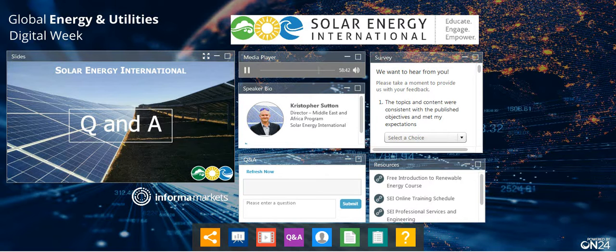What was the next one then, Michelle, or the other part of that? Yes. Can you use your solar system at night? Only with a battery. The PV modules, the solar panels, only produce output that is instantaneous to the sunshine. So if it's a grid-connected system with no batteries, we get solar during the day, and then we use the utility grid for the rest of that. If we want to use a system at night, then we have to have an energy storage system like a battery bank.